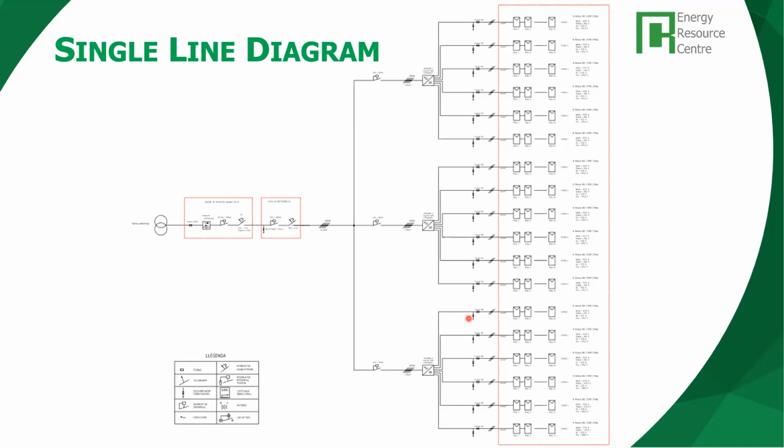Every inverter has 6 photovoltaic strings connected, but only 3 MPPT trackers, and we connect 2 strings to every MPPT tracker in parallel. This connection is in DC, direct current, and this inverter converts this DC into 3-phase AC, 400 volts.